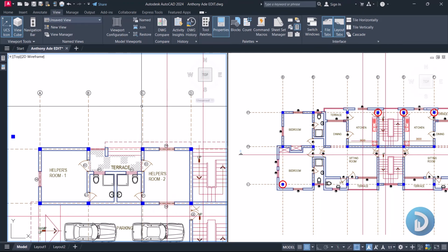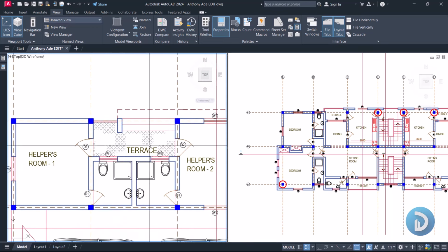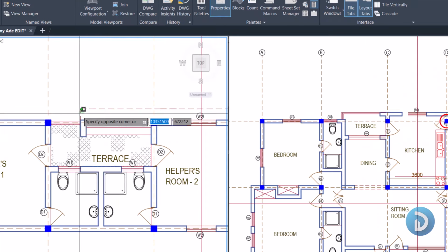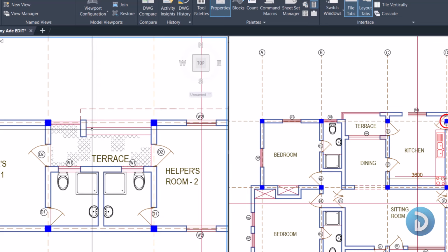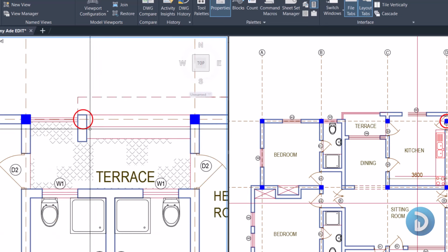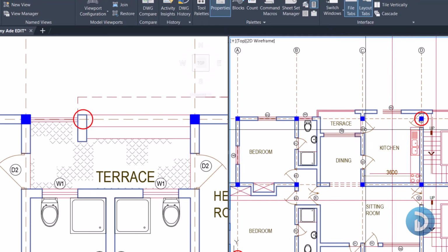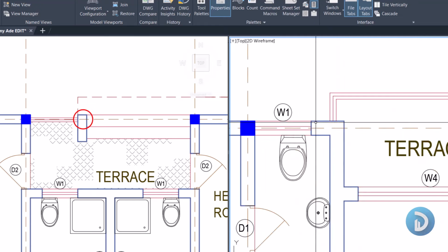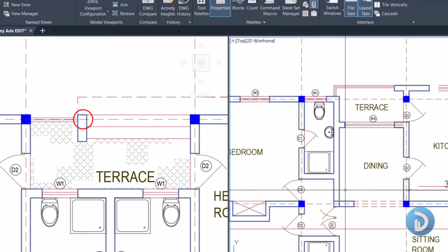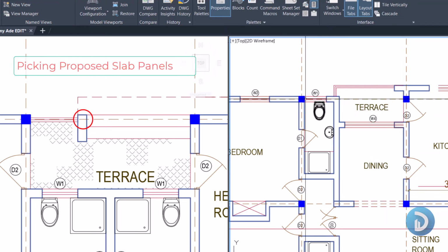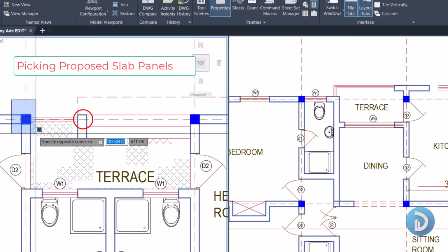Then moving between grid line B and grid line C, you will observe that from the ground floor, we have a provision for cantilever here. We can either support this by a cantilevered beam, or we can introduce a column somewhere here that will also help to hold this cantilever that is coming here. When we get to this part on the first floor, this column that will be introduced here will also provide support for this beam that will come to this other part. Should in case we intend to treat here as a panel, and we intend to treat this other part as a panel. Okay, so I will prefer we start off a column from the ground floor.